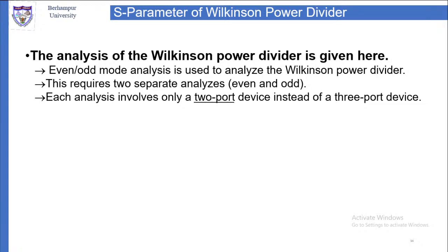This requires, as we saw in the last class, 2 separate analyses. One is even mode analysis, one is odd mode analysis. Finally, we will add these results. Each analysis will involve only a 2-port device instead of a 3-port device. As we have seen in the last class, even odd mode analysis is applicable for 2-port devices, so the 3-port device is divided into two 2-port devices, and we will do the analysis.